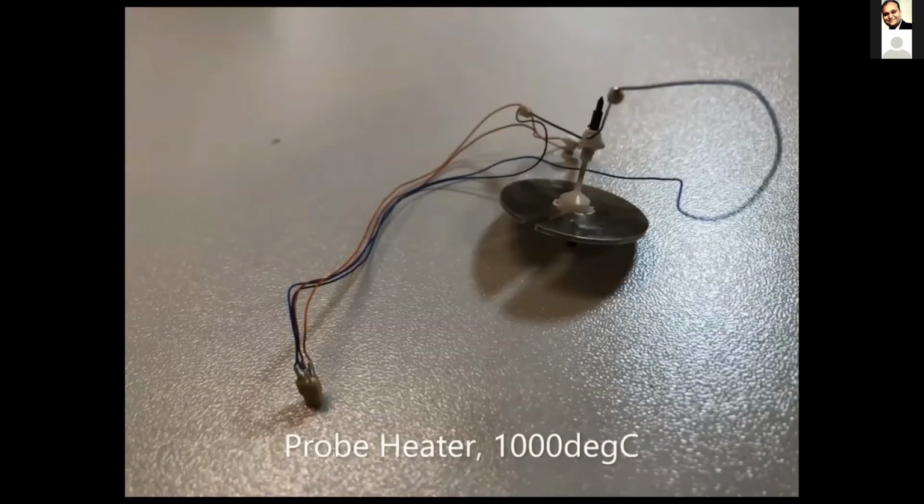This is the probe heater. It also uses a resistive heating element and an integrated temperature sensor and an integrated thermal break to prevent heat from leaving the tip and moving back into the rest of the system. You can also see that there is a metal disc, which is an infrared shield to block infrared radiation from heating the transducer housing. You can see that the tips are threaded on and off of the end of the probe heater, so they're exchangeable.